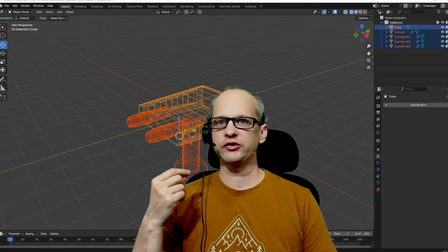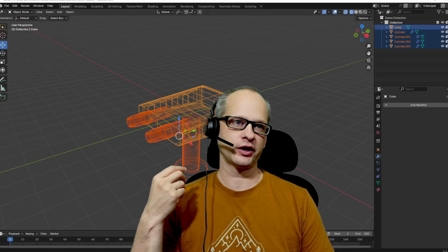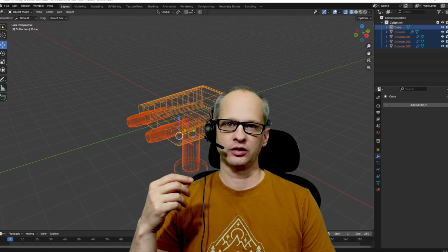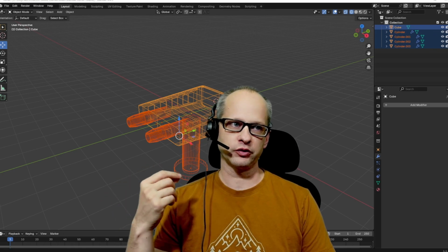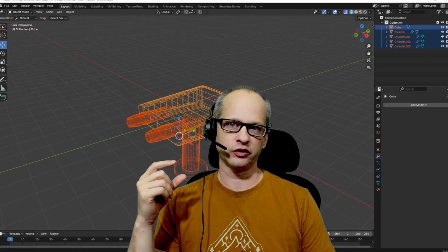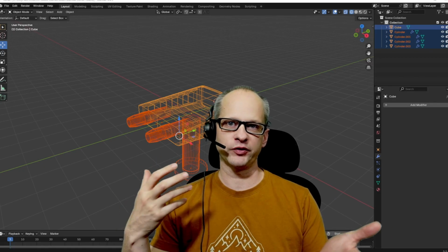All right, that covers it for the video. So it was just a general introduction into what you need to do to set up Blender to make it work nicely with Roblox Studio. So just adjusting the scene properties there, adjusting the units, adjusting the grid so it looks proper, so it's down to the 1 stud size, and then exporting, so you're using the right configuration when you're exporting there.